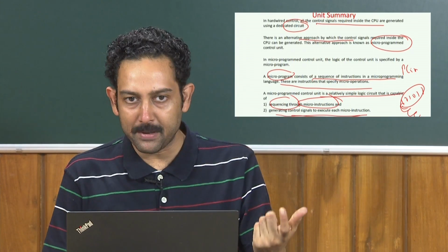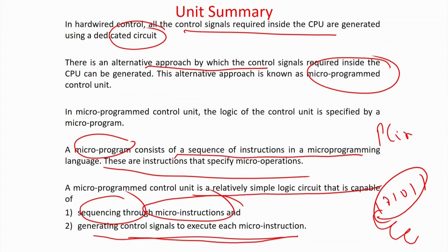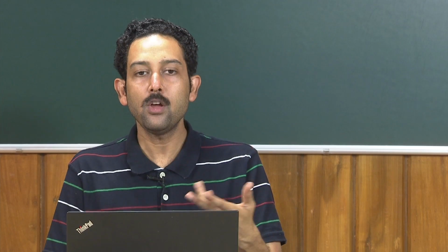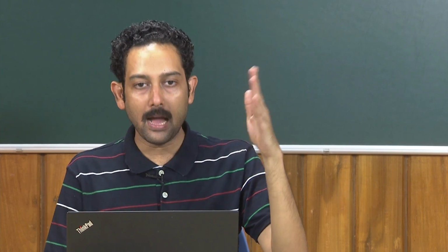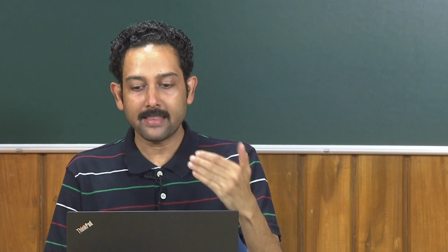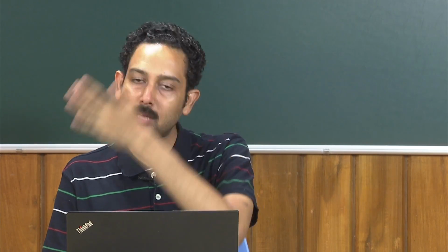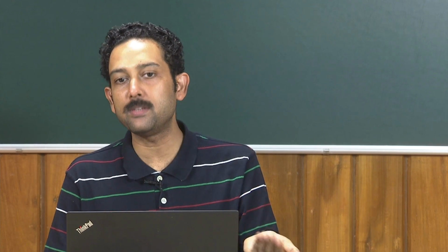But whenever there is a jump instruction and you also need to check some flag conditions, which is simpler in a finite state machine based approach, here we have to have a separate arrangement. Just by looking at the control signals, that is the input output signals, and then also the flag signals, you decide whether the next location is the one which generates the corresponding signals, or you have to jump to some other location where the control signals have to be generated accordingly.